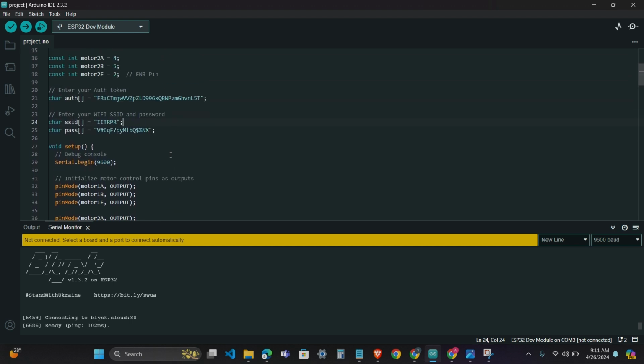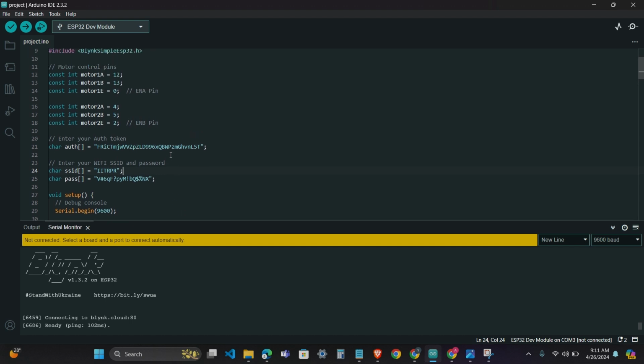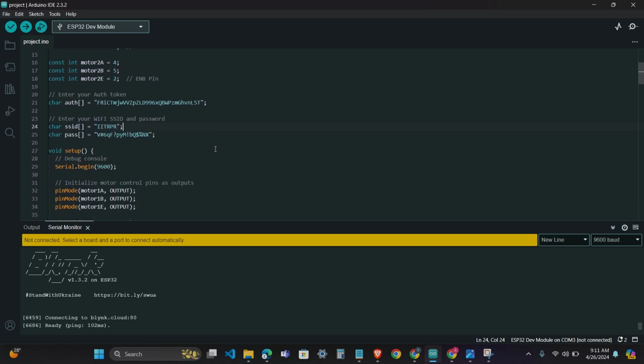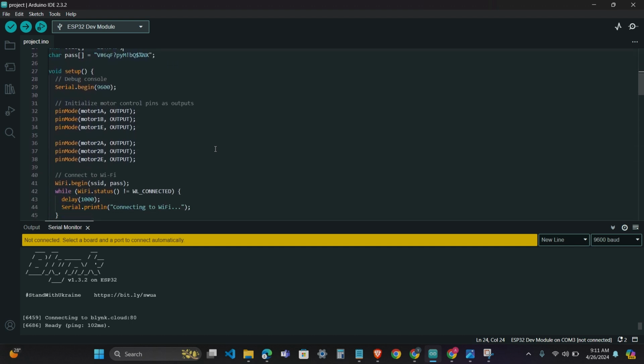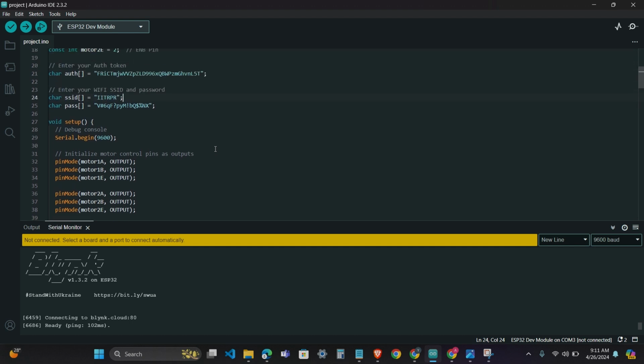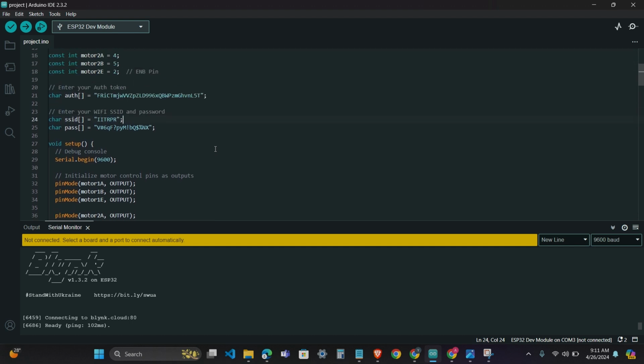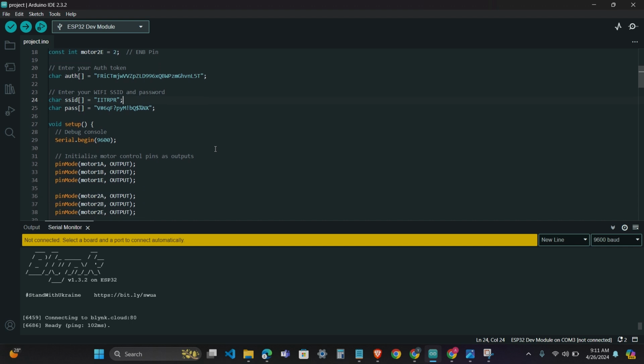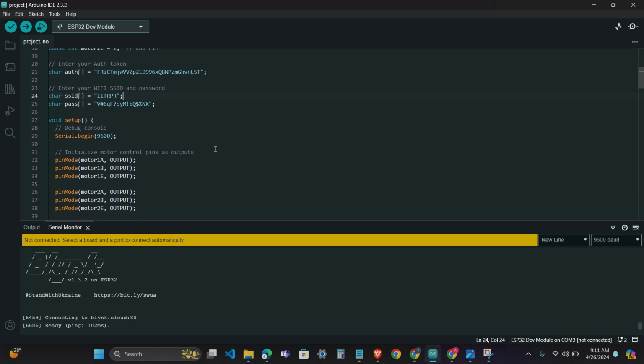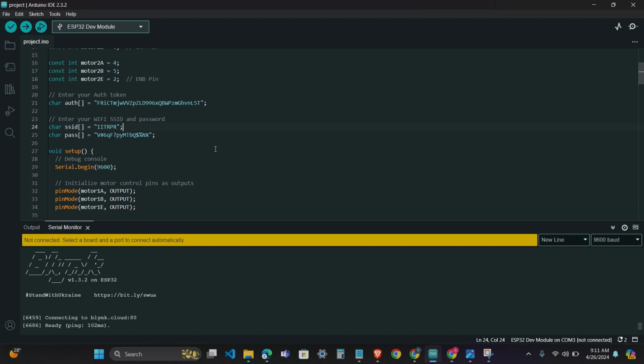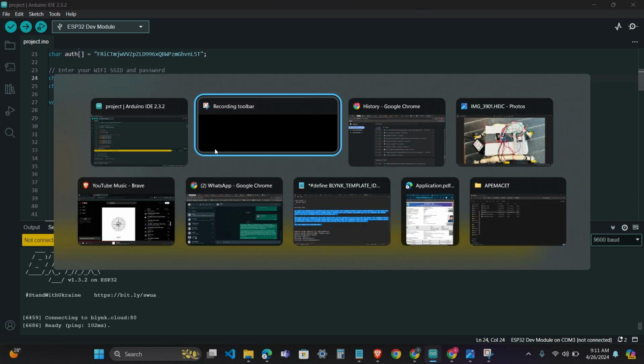but the problem we faced while controlling our rover through the Blynk server is that our rover needs input from six different pins to achieve four different functions, which are forward, backward, right, and left. But the Blynk app allows only five button states to be enabled at a time, and we cannot toggle all those six different states individually if we want to control the rover seamlessly.